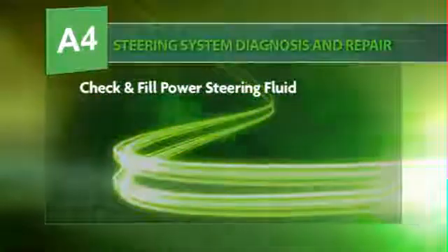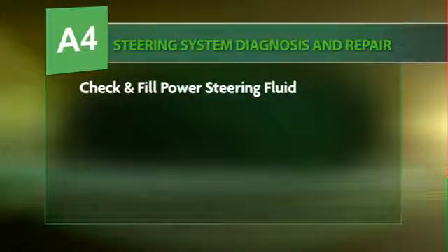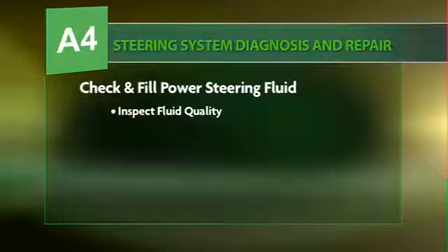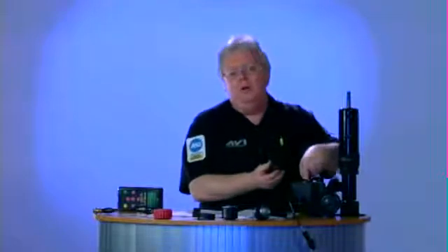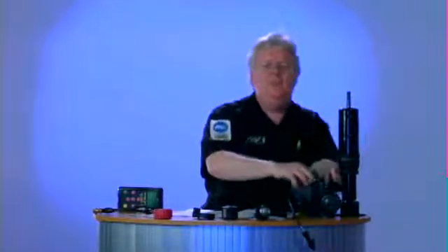To check and fill, obviously, to check power steering fluid, it's much like checking automatic transmission fluid. You need to have the engine, aka the power steering fluid, warmed up between 120 and 180 degrees Fahrenheit. So it's got to be warmed up. Got to go for a road test. You got to be on a level surface. And unlike the automatic transmission, you don't check it while the engine's running. Ever taken the power steering fluid reservoir cap off the pump, or the reservoir if it's remote, while the engine's running? You know it's just splattering all over the place. So the engine's got to be off, but it does have to be warmed up.